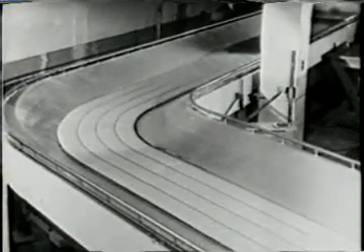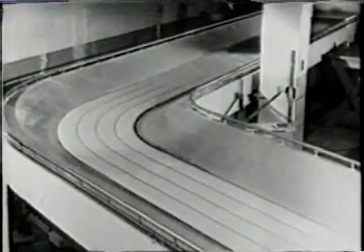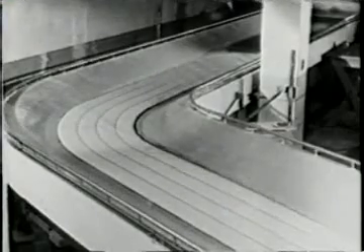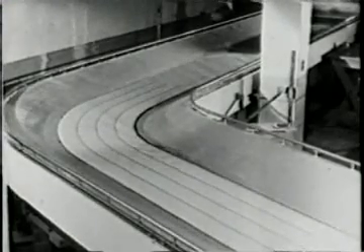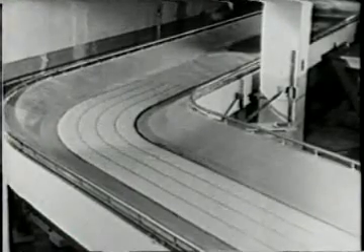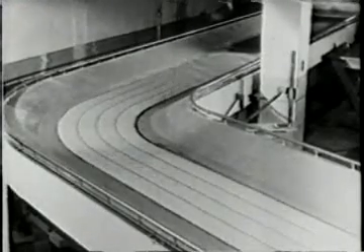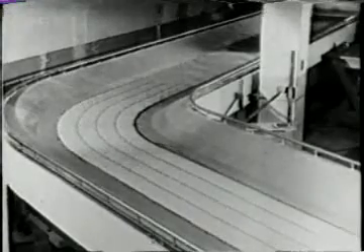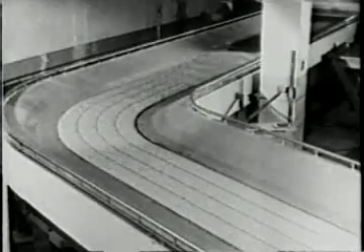In this open channel, water flows around a bend. Upstream, the flow is parallel to the walls of the channel. Because of the boundary layer on the bottom of the channel, the upstream flow has a horizontal component of vorticity in a direction transverse to the flow. But upstream, there is no vorticity component in the vertical direction, nor in the streamwise direction.